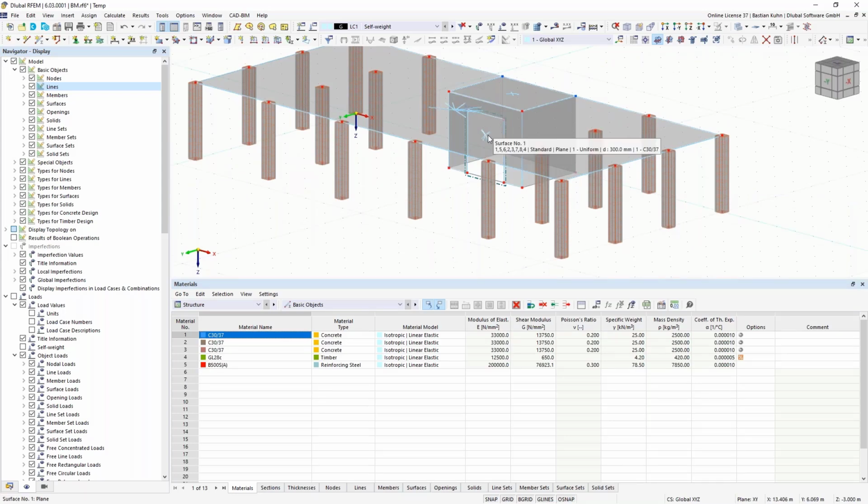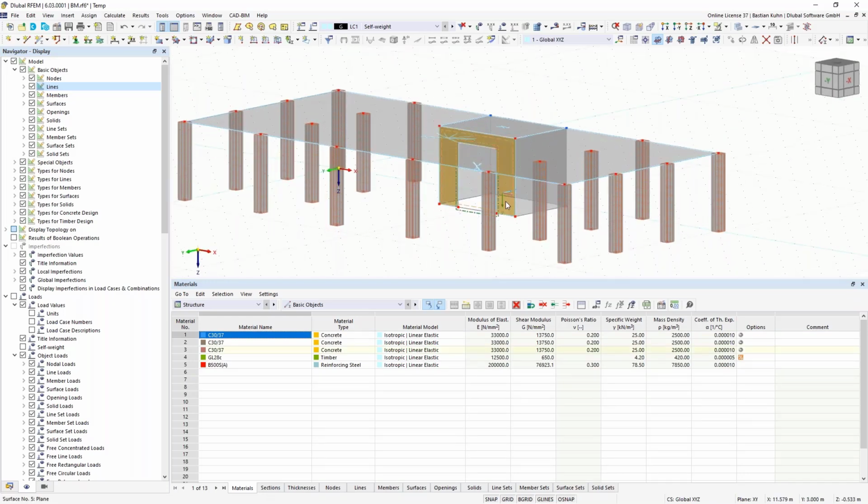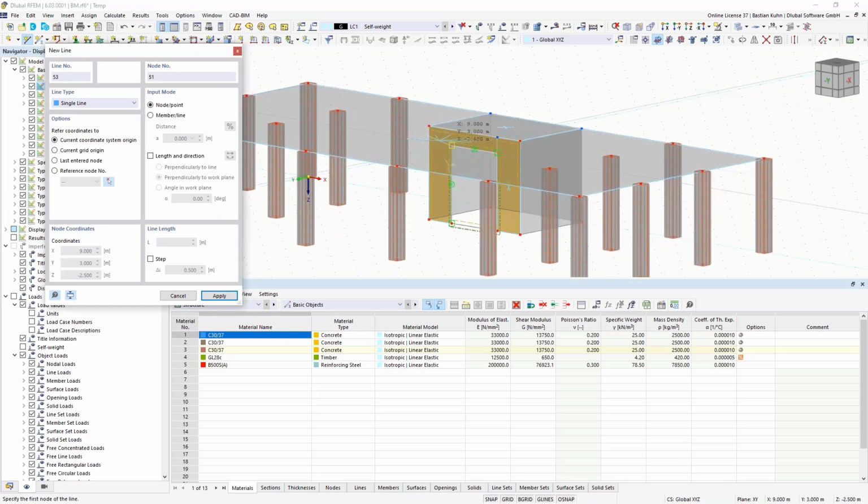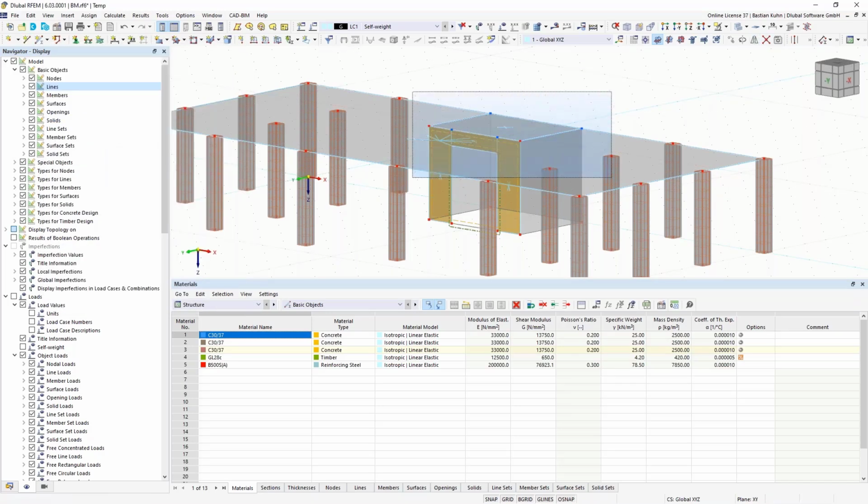You probably saw that here are some kind of cells generated. That is something what is already needed for the building model add-on afterwards. And in order to arrange the cells correctly here on the opening, I need to divide this surface. Let me check the number. The surface number 5 by vertical lines completely. And now I could copy the node, of course, just 50 centimeters above, but there's an easier function to use, the object snap with perpendicular inside here. And once I activated that, it's generating the line perpendicular to the existing one, and that fits, so that just goes a little bit quicker.